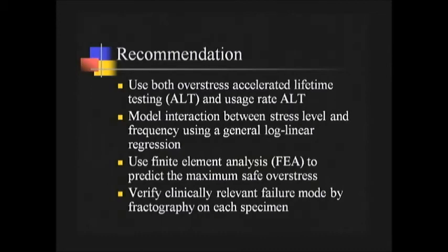And then just to remind you, and this is a good segue to Suzanne's presentation, you should do fractography on each and every specimen after you test it, to make sure that the failure mode you observe is the same as the one that is observed in clinically retrieved specimens, to make sure that the data you're taking, even though you're taking it faster, applies to the clinical case.